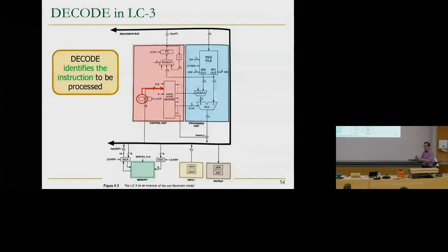Decoder also identifies which part of the instruction are denoting the source registers and the destination register. All of those are the outputs of the decoder. Like, what is your source register 1 ID? What is your source register 2 ID? What is your destination register ID? If you have an immediate, what is that immediate? If you have a shift amount in MIPS, what is that shift amount, for example?